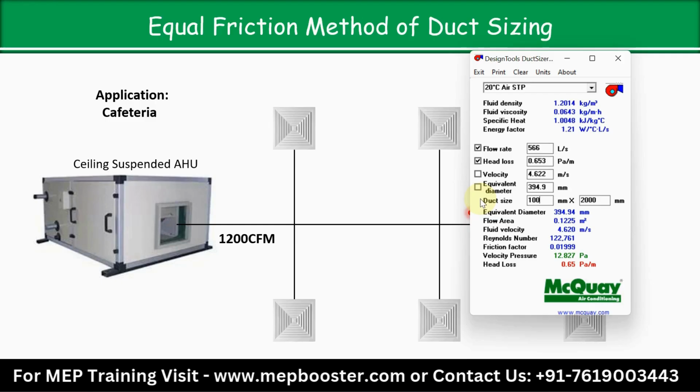The reason is to optimize the airflow efficiency, because a duct with a higher aspect ratio increases friction loss, as the air has to travel along longer surfaces. Keeping the ratio close to 1:1 ensures smoother airflow, reduces turbulence and pressure losses. So that is why always try to maintain the aspect ratio close to 1:1.